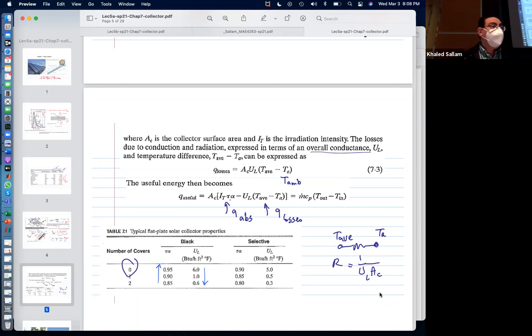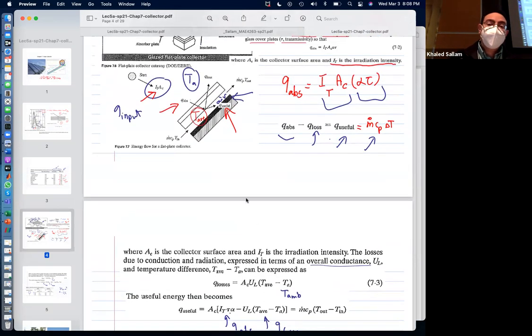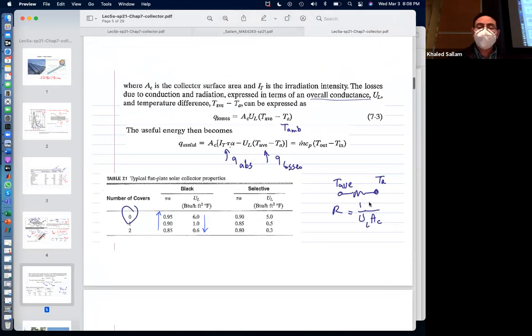Okay? And so if the mechanism is conduction and then convection and then conduction, adding all those resistances together would be the total resistance between the two temperatures. So the wall painting and then the brick and then the insulation layer and then the cover from outside, you add all those resistors together and that will be your total R. You can alternatively call it 1 over UA, where U is the overall heat transfer coefficient. So when you say that Q is delta T over 1 over UA, alternatively you can say Q is A U delta T.